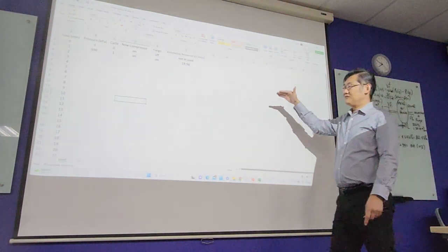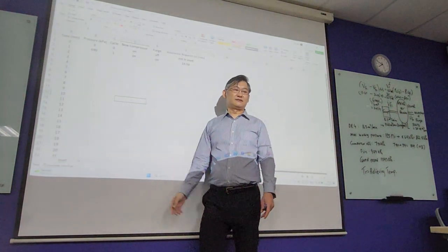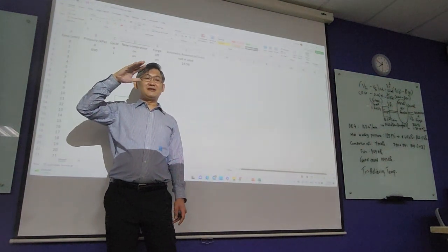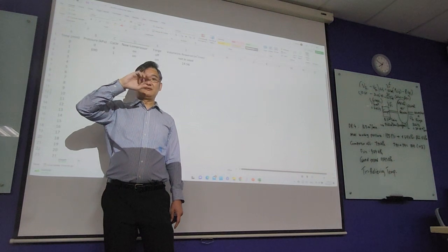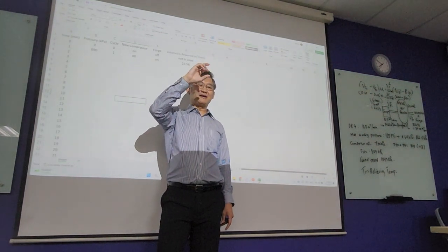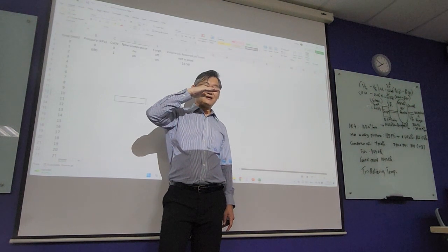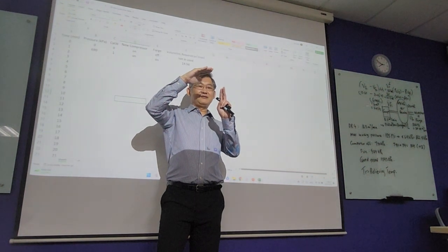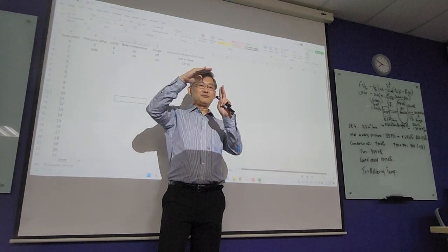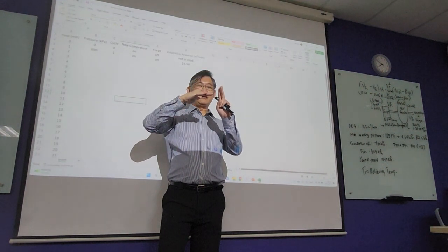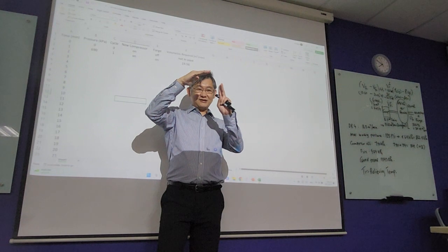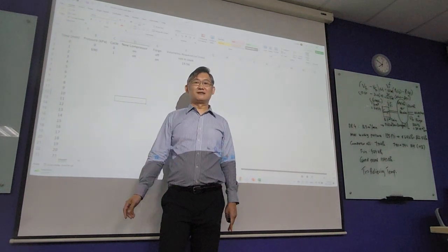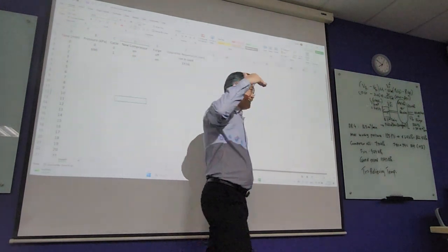As you know, your tank volume cannot be lower than 620. After that, if let's say the pump keep running until 790 must stop. So in this case, sometimes you will count a cycle that you can see within 1 minute, let's say about 30 seconds. So the pressure grow until 790, it will stop. After that, it will bring down again, the compressor off, then you will see the pressure lower down again until 690, it will actually run again. So this is how you are going to use this list.